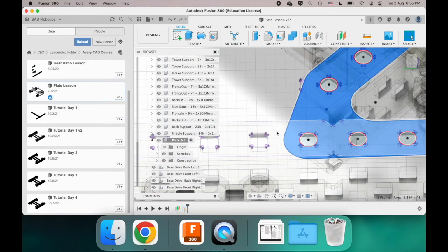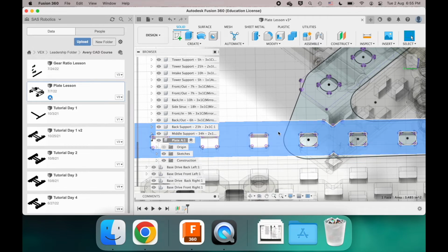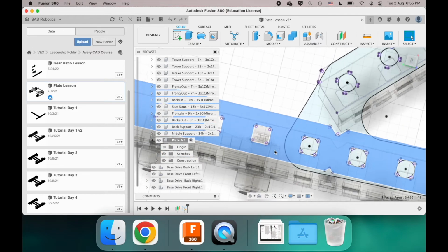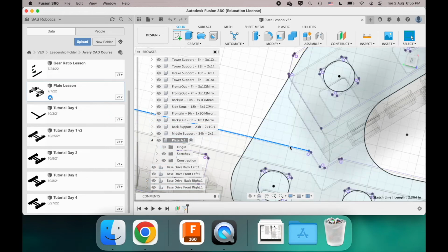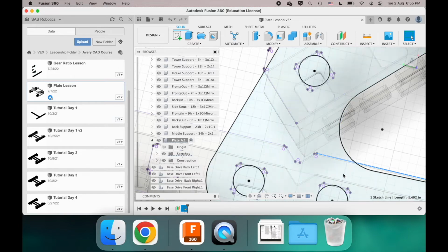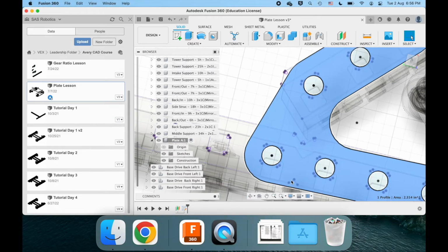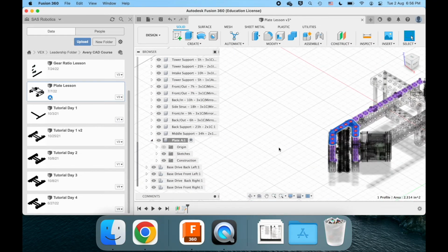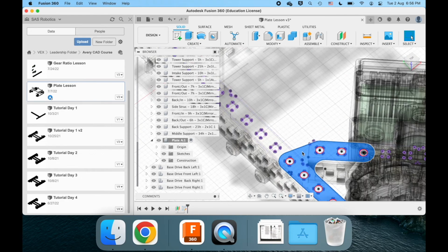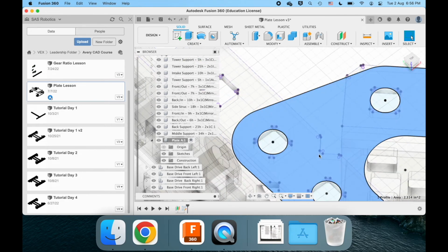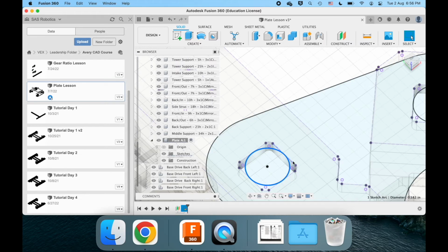Now, if this whole surface that we projected was not in sketch mode, then all of these lines, like this line here, that goes to here, that goes to here, that goes to here, right, would be solid, and that would actually break up this plate into two pieces. And maybe that sounds fine, but then just remember that that would mean, so would this box here also be solid. And we have to select like this little corner here, here, here, here. It'd just be very annoying.